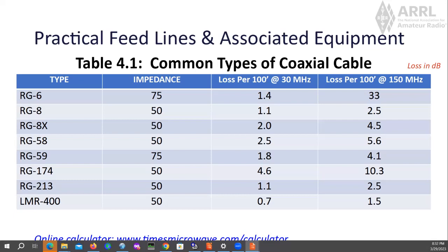Reality is when you put the antenna up, if you can get it high enough, and that is quarter wave is the recommended, which for a quarter wave 160 meter antenna, none of us have poles tall enough to do that. So that affects how the antenna works because it's closer to the ground. But that 468 is just a good general guideline number.